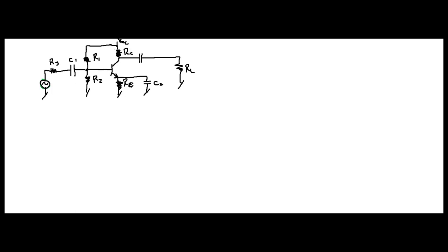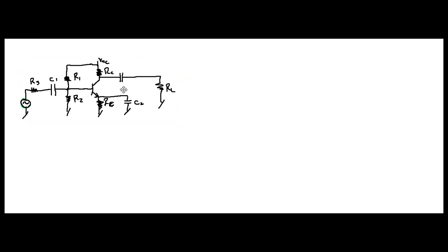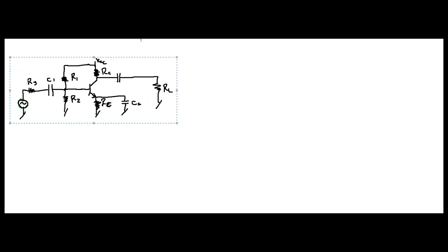Alright, so that is your basic amplifier there, a common emitter amplifier. Let me move it over so we have as much space as we can get. Obviously, when you're looking at this, you're going to tap off it right here. This is your Vout. It's going to supply voltage to your load, right? Now, let's redraw this as the high frequency equivalent circuit.